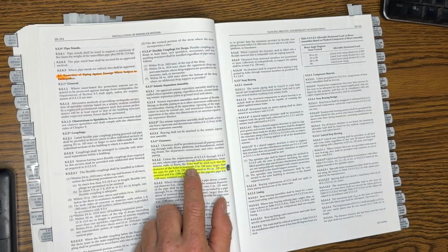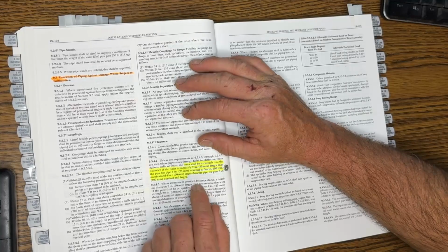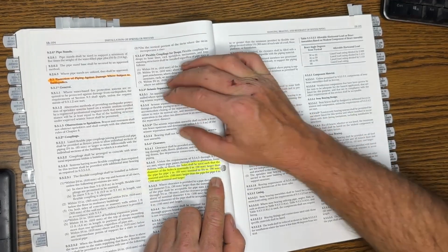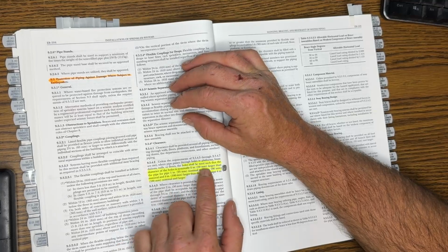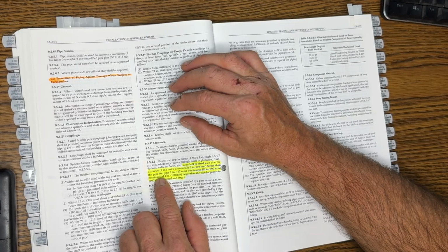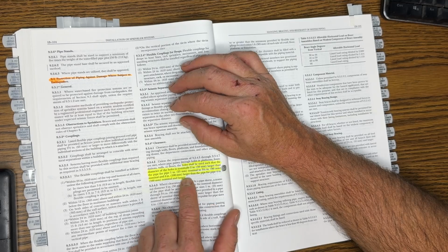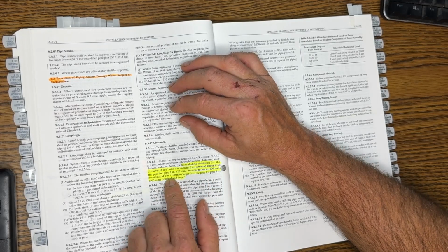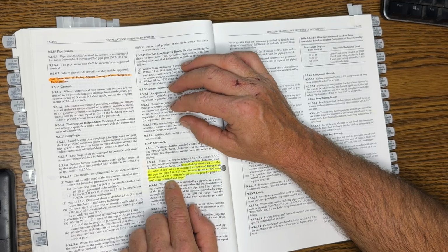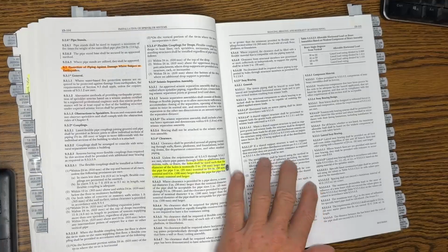A building plans examiner identifies a specification for an 8-inch hole to be cut in a W24 by 162 beam to support a 6-inch sprinkler supply line. What should be done? So how much of a hole do you actually need? If you look at 9342, holes shall be sized such that the diameter of the holes is nominally 2 inches larger than the pipe for pipe 1 inch nominal to 3.5 inches nominal, and 4 inches larger than the pipe for a pipe 4 inches nominal and larger. So if you have a 6-inch sprinkler pipe going through this, you need to have a 10-inch hole. So it's 6 plus 4. That's how you'd figure that out.